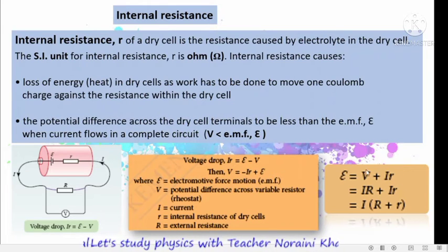If you look carefully, this equation explains that of the total voltage supplied, some is used to overcome external resistance, some of it is used to overcome internal resistance. So we get this formula, V equals IR, we substitute here, factorize I, so EMF equals I bracket R plus small r.